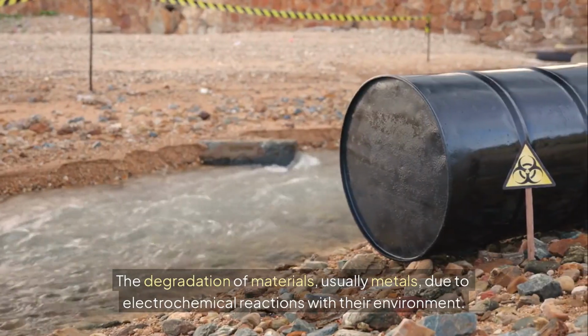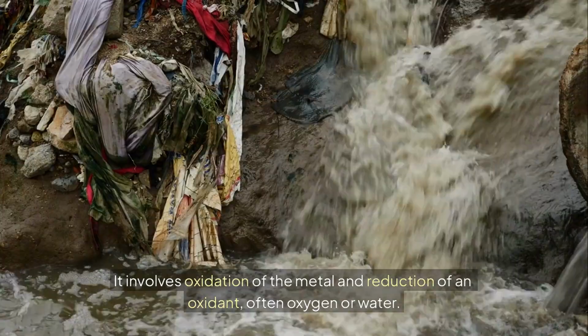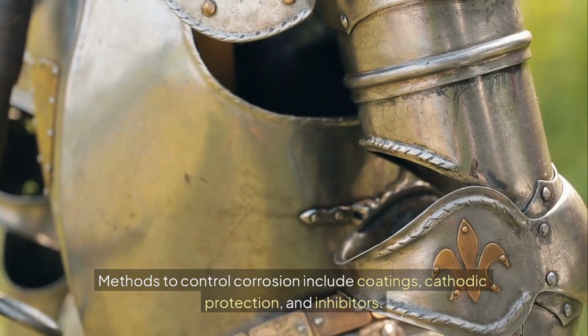Corrosion is the degradation of materials, usually metals, due to electrochemical reactions with their environment. It involves oxidation of the metal and reduction of an oxidant, often oxygen or water. Methods to control corrosion include coatings, cathodic protection, and inhibitors.